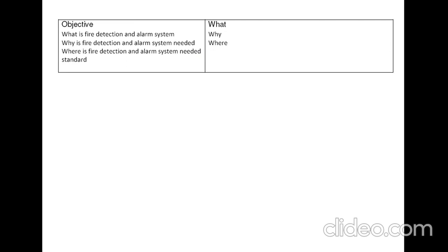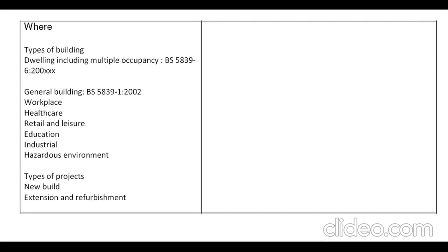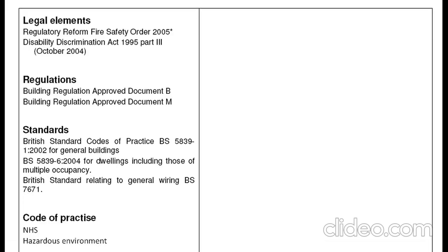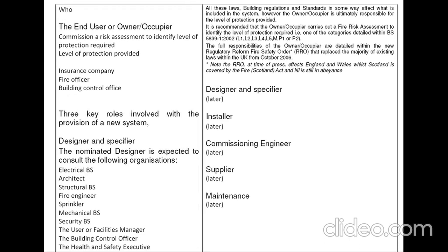So these are the things you need to consider when you are locating a fire alarm device. Number one, you've got to consider the environment, and under the environment, you need to consider the height, the activity within the room, and the hazards within the room. Number two, you've got to consider the category of the system. Number three, you've got to consider the coverage of the detector within a room. Make sure it covers the entire room.